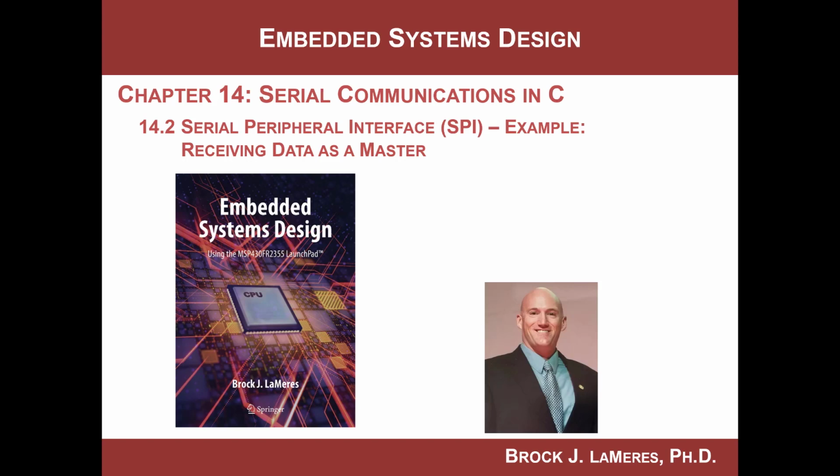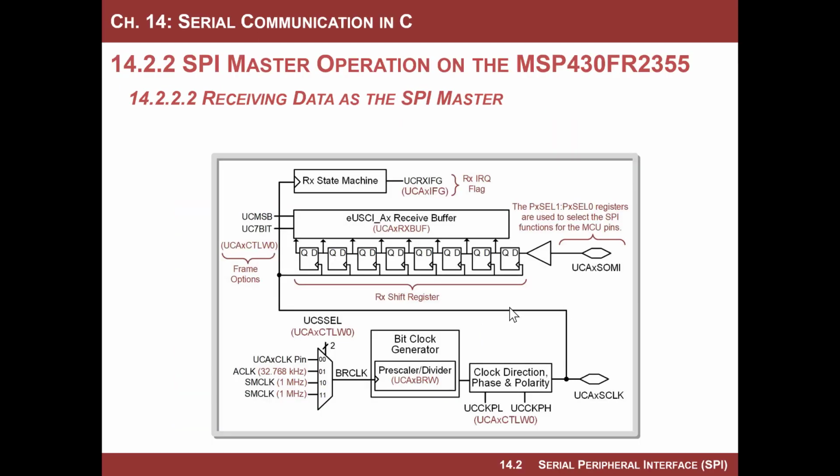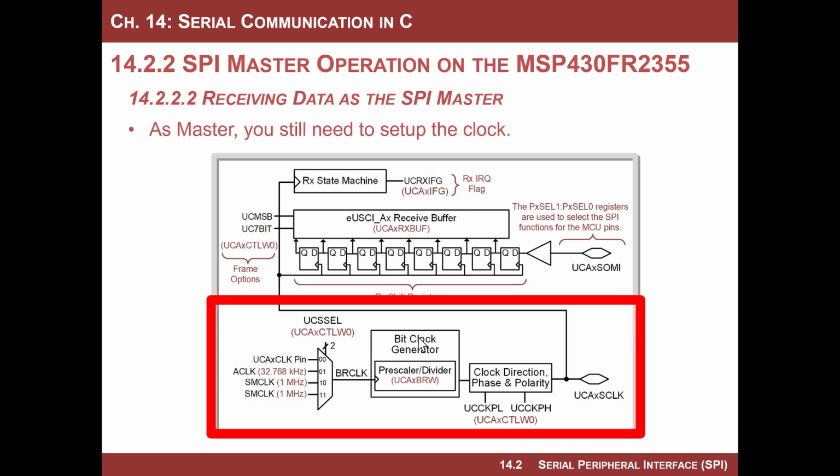Hey, this is Brock Lemire's Embedded Systems Design. We are looking at the SPI peripheral on the MSP430, and in this video, we're going to look at how to accomplish receiving data as a master, and then we're going to do an example where we drive data into ourselves, essentially. Okay, so remember when you're receiving data, you, as the master, generate the clock.